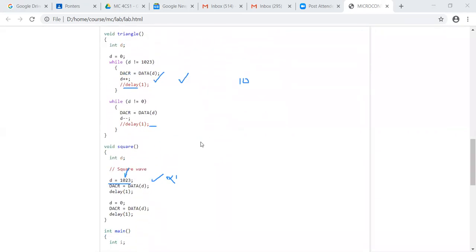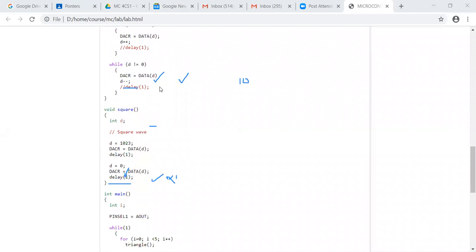And then there is only one register on the device you need to worry about. It has data, it's a DAC control register where there is a place for data between the bits 6 and 15. So this is a data register starting from the bit position 6. You have to put a 10-bit data there. And of course, we have a macro. Given the data value, it will shift the data by 6 bits and place it there. So let us see the macro there.